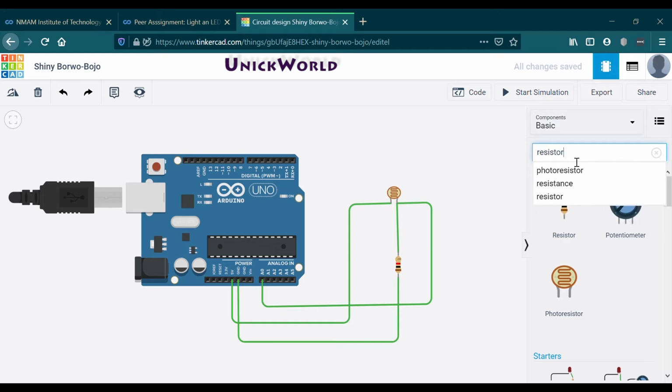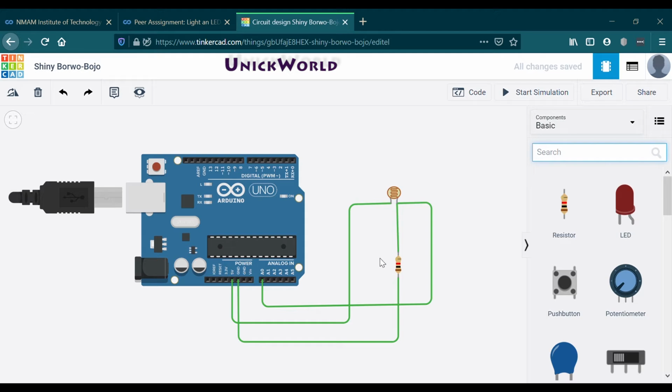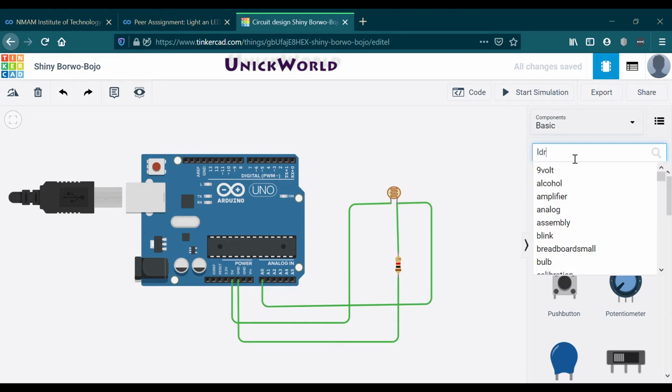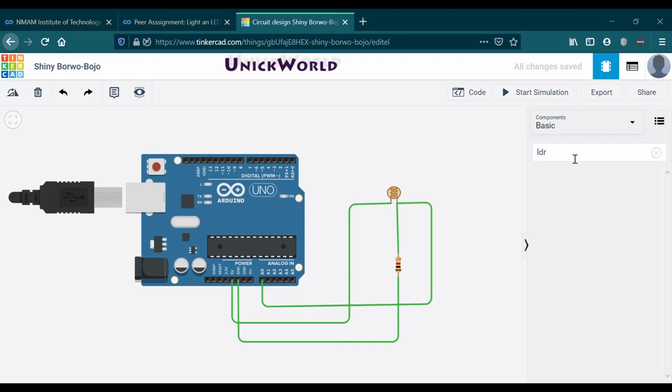And this is the resistor we would be using in the circuit. You could see that this is a normal resistor, maybe a 220 ohm resistor, and we would be placing it. It's always a thumb rule in electronics, to limit the current we use a resistor, in order to preserve the component, in order to not see smoke coming out of it.